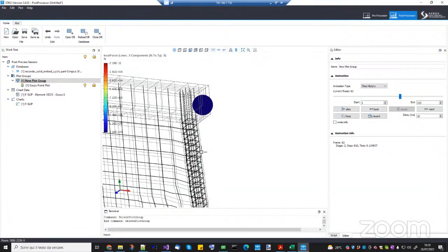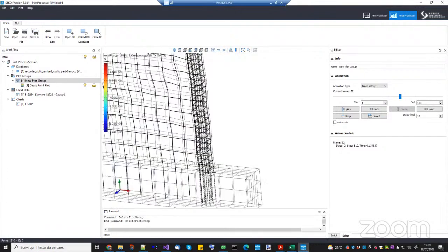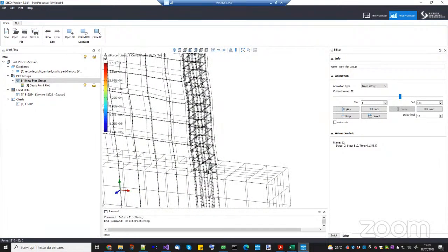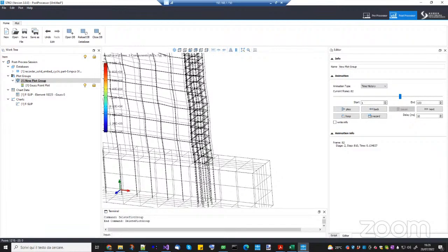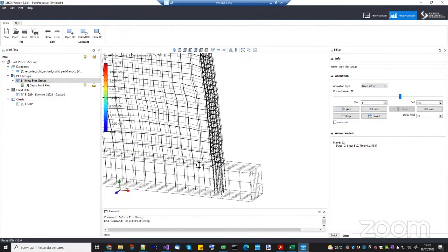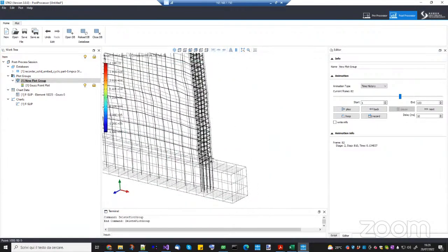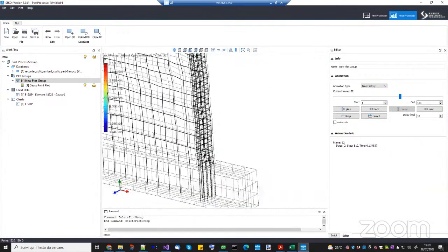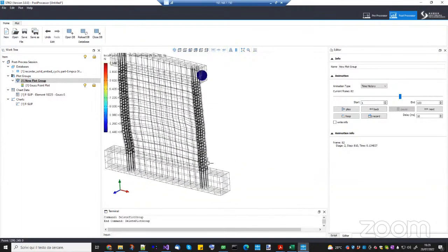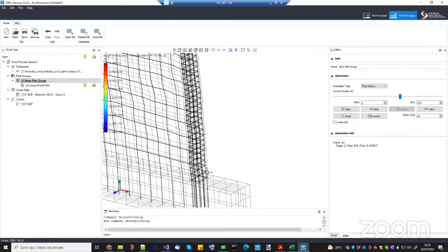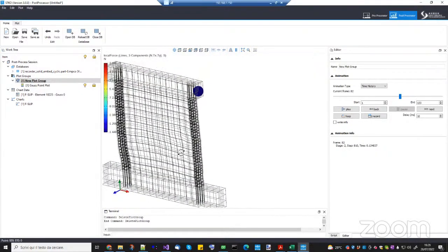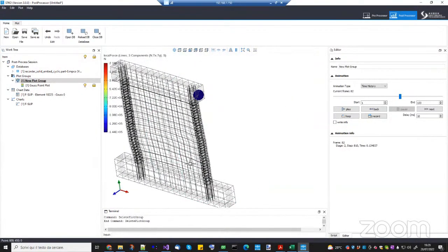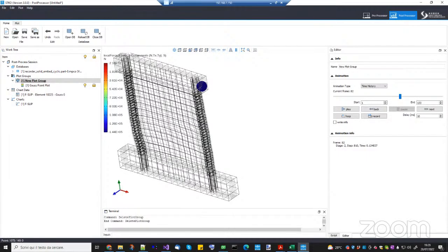Here, for example, because you modeled the column on the side with solid elements, if the boundary or the column of the wall is in compression, you will mobilize the confinement from the stirrups. Exactly. And in a way increase your compressive strength. Have you ever tried on an example like this to plot the axial stress-strain in compression and see that this increase of compressive strength is visible in the numerical result? It's not negligible. Actually, it is visible.